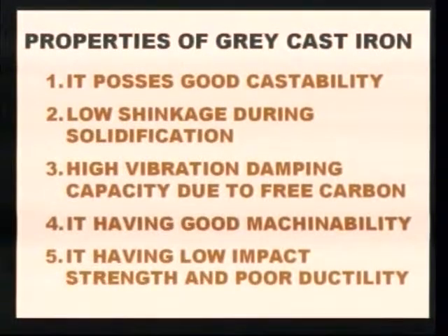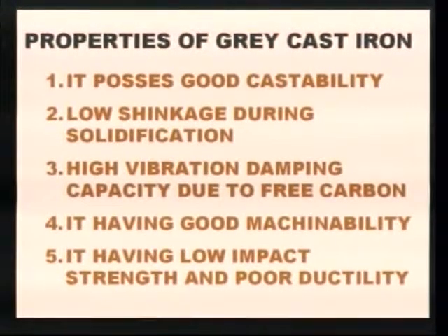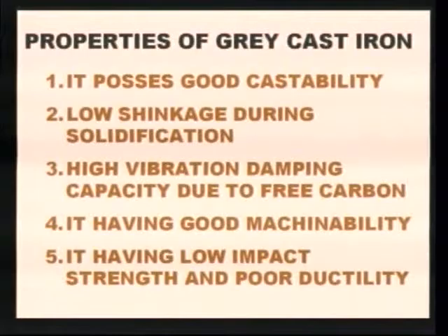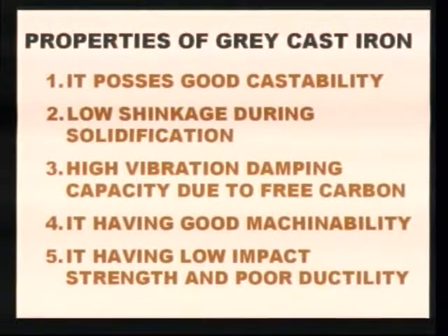First, it possesses good castability, low shrinkage during solidification, high vibration damping capacity due to free carbon, it has good machinability, and also it has low impact strength and poor ductility.